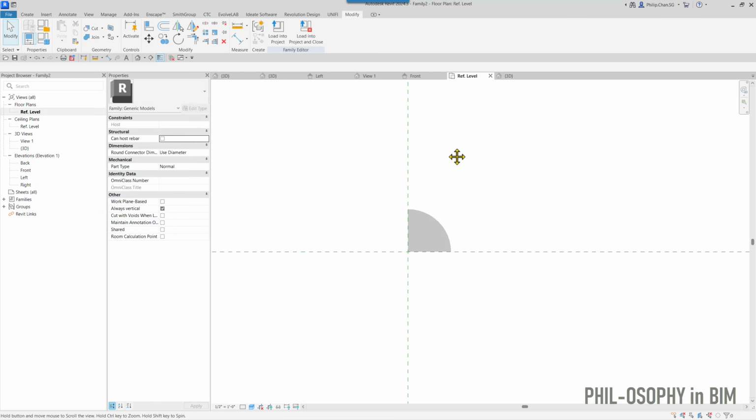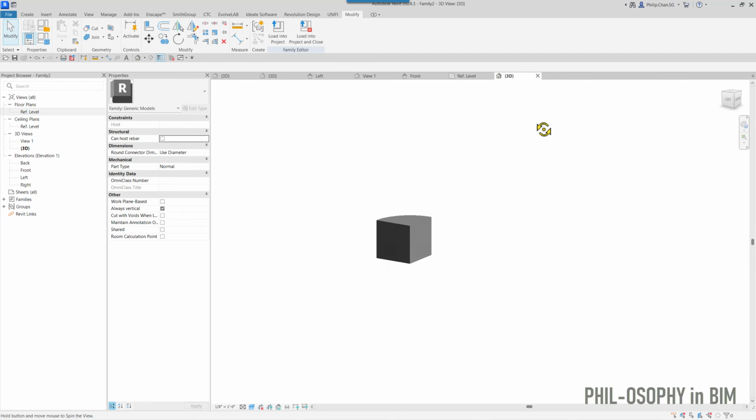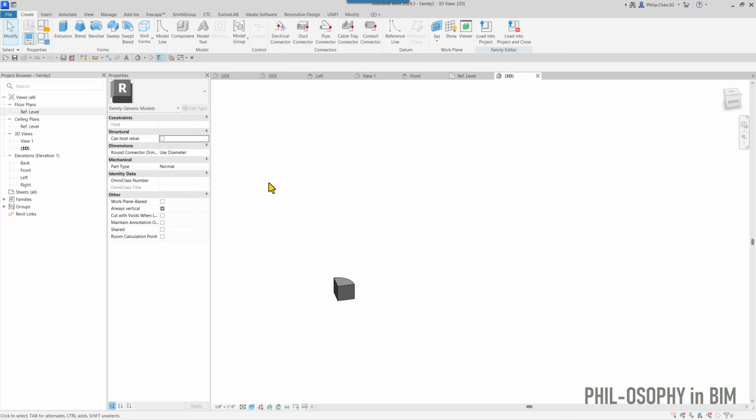So what that means right now is taking the same concept. If I'm using this pie here, I can now, instead of reference line, use this little pie here as a framework to set up my rotation parameter, or kind of a rotation framework. So the way that works with this is, first of all, I'm going to go to the Create tab. Similar to the reference line, I have to tell Revit what my work plane is going to be. So in this case, I'm going to go ahead and use set work plane.